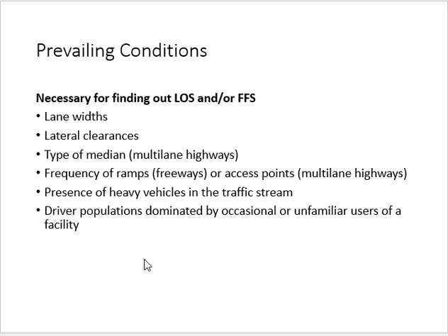This emergency lane, we call it the shoulder. This is not considered part of the road. So your lateral clearance starts from the yellow line. After the yellow line, if you have the emergency lane, it is the clearance. Emergency lane is part of the clearance, not the road. Got it? And in the book you will see it is called shoulder. So shoulder means the emergency lane. And if it is there, it is part of the clearance, not part of the road.